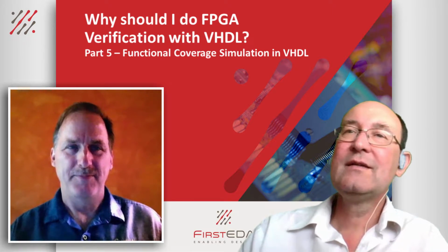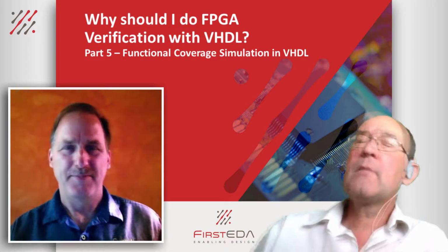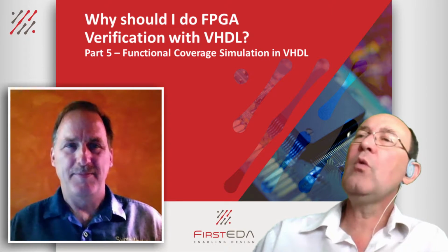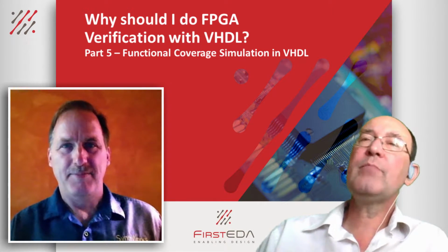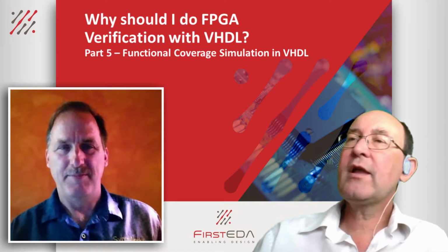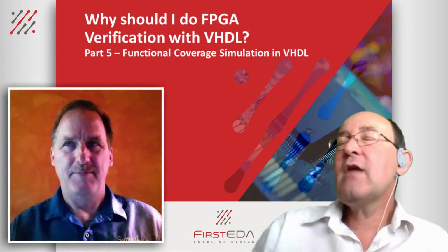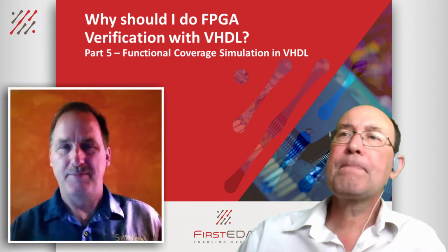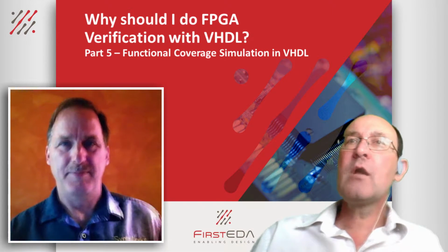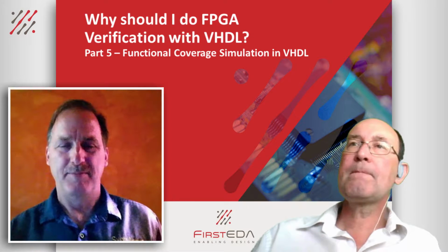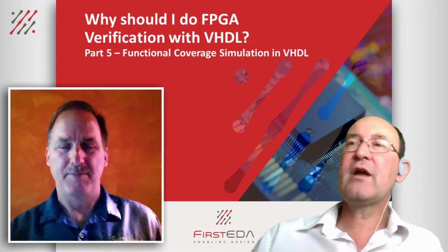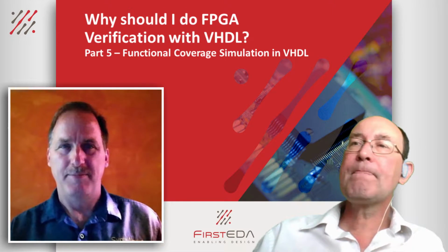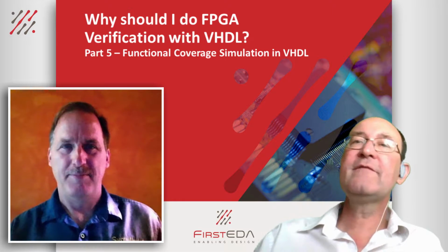That's a pleasure. As we discussed in our previous videos, FPGA designers today are facing the huge challenge of verifying their designs. Large or small, making sure they work correctly is an important part of the design task. And we're looking at how they complete that verification. In earlier videos, we saw about bus functional models, constrained random verification. And we learned that if you use constrained random, you need to know when you've tested everything. And one of the methods for doing that is functional coverage. In this session then, we'll look at functional coverage modeling. So Jim, how do I write a functional coverage model for my FPGA design?